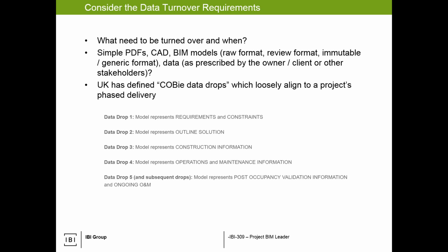the client. The UK has defined what they call COBie data drops. So if you remember from previous sessions, COBie is Construction Operation and Building Information Exchange. So it's focused more on facilities management, and they have a predefined definition of the 5 data drops. And a data drop in North American terms is just a data deliverable or a turnover of information. So the UK has it defined.